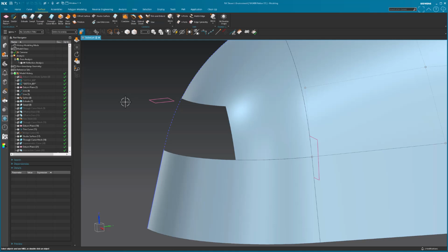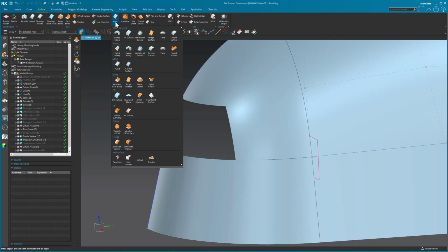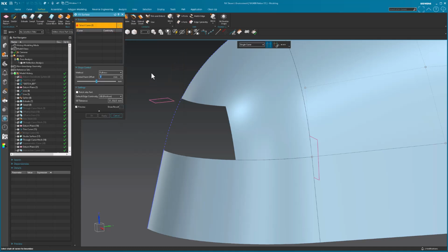To fill that area in, again, I can use several tools. Now, this is just for the example here, because I know someone's going to ask me about it. There's a tool called Fill Surface. And fill is pretty nice because it allows me to say, oh, wait a minute, I want this at G1. It changes to G1 because I'm attaching to surfaces.